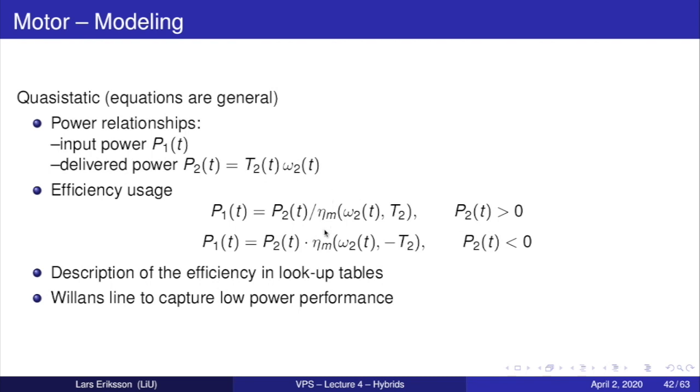When we go the other way around, when we're going regenerative braking, we are getting power from the driveline and we multiply it by the efficiency of the device to get the power that is transmitted to the power electronics.